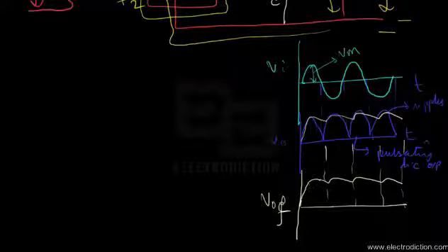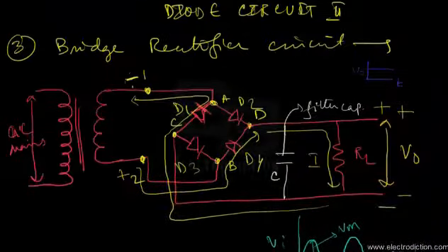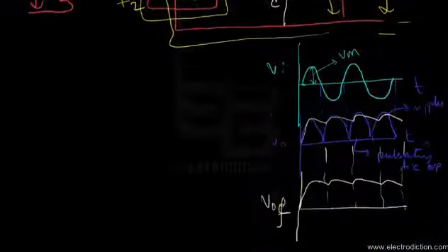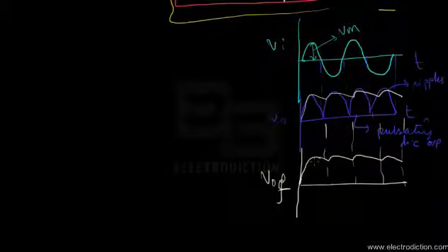So here we can see that although we don't obtain a straight DC voltage, which is a straight line of course, still we are able to get somewhat close to it, as the variation of the output voltage is somewhat reduced. So it's more or less a straight line, or rather close to a straight line. And now these minute variations that we can see here won't be perceivable, but it helps in reducing the ripples to a great extent.